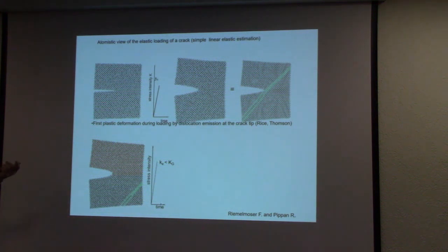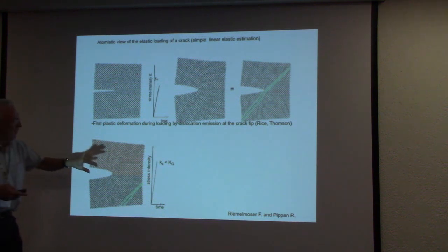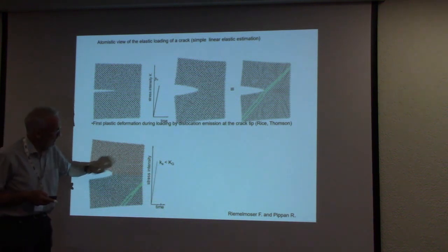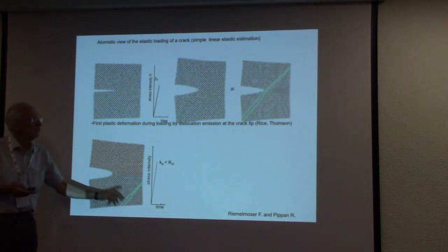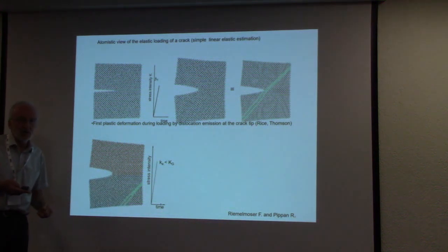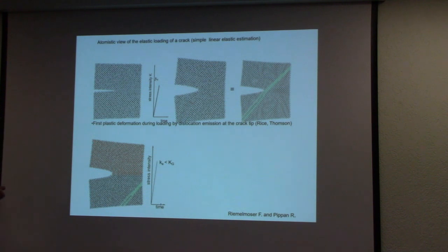You will come to that in a few seconds. They cannot describe it, because it is a continuum mechanics concept in the standard version. If you take a gradient into account, then you can also come to a size effect. They can introduce a size effect. The next approach, which really can tackle this size effect, is the mechanics of the discrete nature of plasticity.